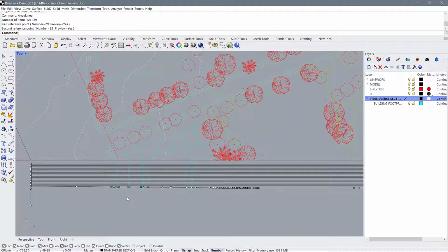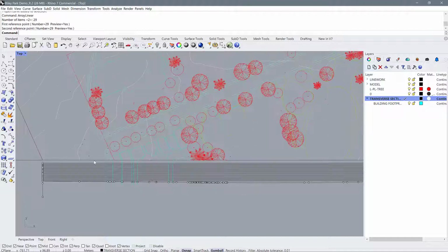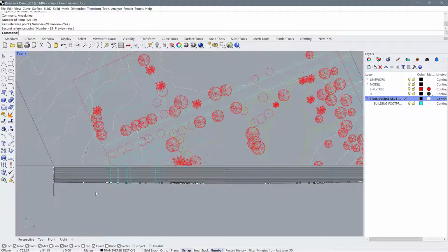But if you haven't done that, which I haven't, then you have to project the building heights to a size that is relevant to your site. So these are single family houses, and I know this area well. I know that these are usually between 2 and 3 stories tall. And a single story is about 3 meters tall. So if these are 2 or 3 story buildings, they are between 6 to 9 meters high.